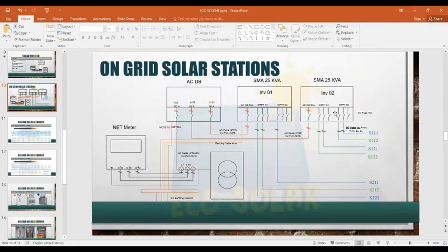A single inverter unit has two DC inputs. Each input is called an MPPT: MPPT01, and the second one MPPT02. Each MPPT can operate with 3 DC strings. So I have 7 strings on 2 inverters.